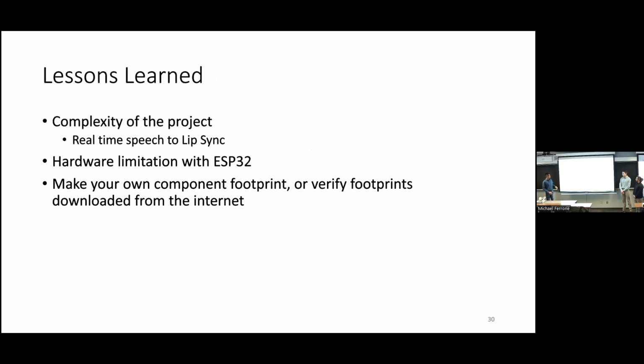And here are several lessons that we learned. One is the complexity of the project. Real-time speech to lip sync was really complicated to achieve, based on the hardware limitations we have with the ESP32, and also the libraries available for it depend on the different languages available. Also, the main thing we learned is that we either need to verify our footprint or make our own correctly, so we don't deal with issues where something is wrong but you don't know where it could be wrong.